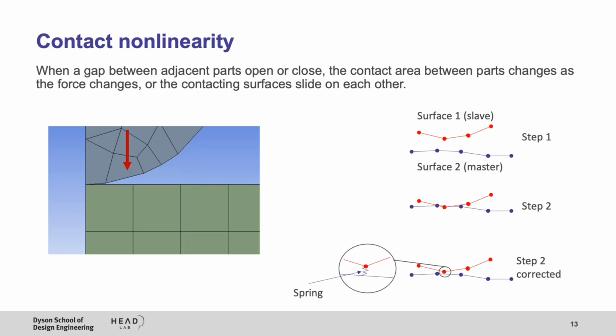Contact is a nonlinear problem in nature. It deals with situations where a gap between adjacent parts opens or closes. The contact area between parts changes as the force changes or the contacting surfaces slide on each other.